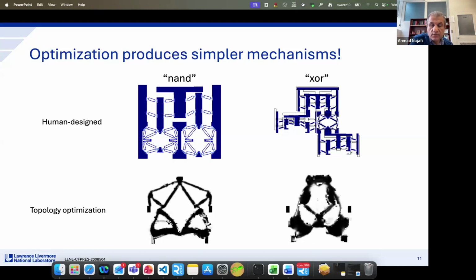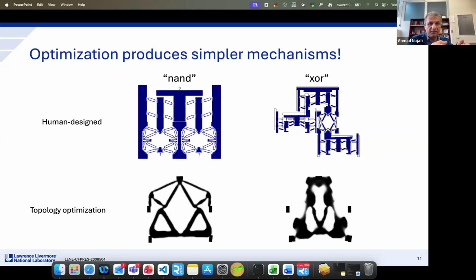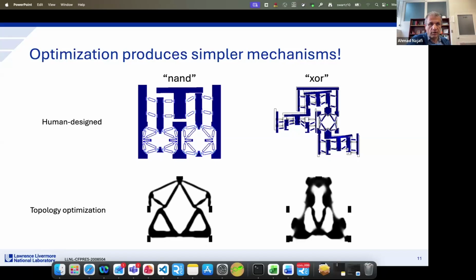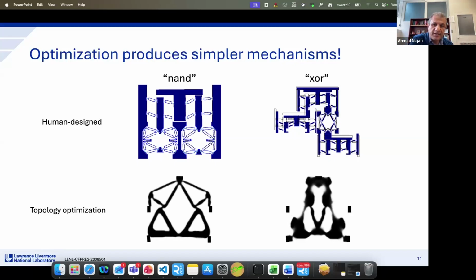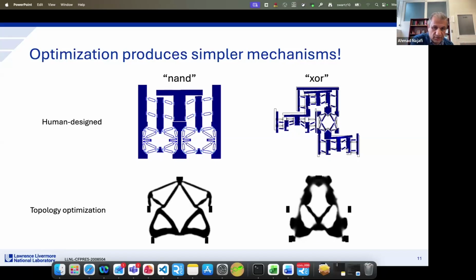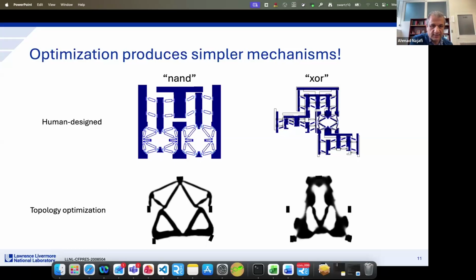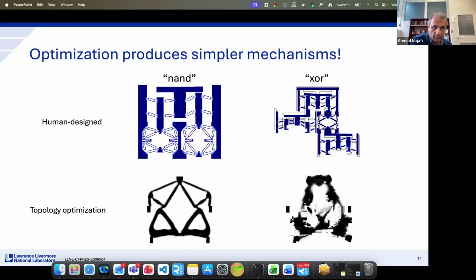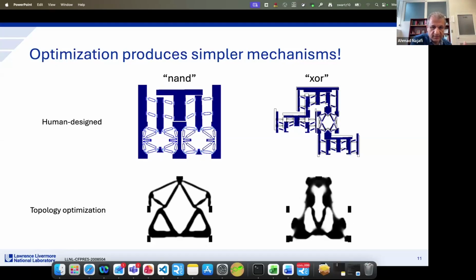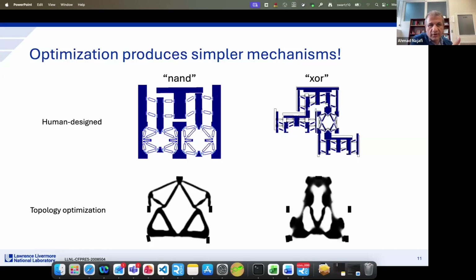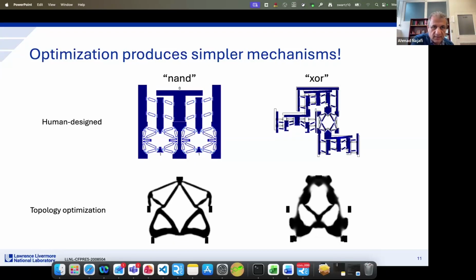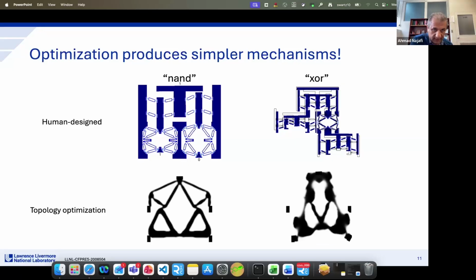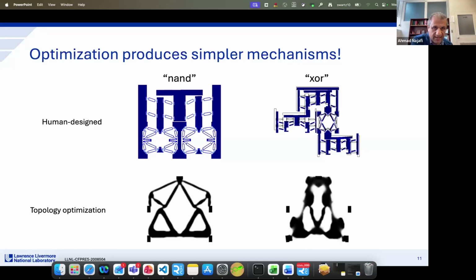Okay, it makes sense. And you saw that one of the issues was that when you try to make it, it was buckling. If you add the buckling constraint or buckling analysis in your topology optimization, probably you can predict or design in such a way as to reduce the buckling in the third direction or any other direction. Yes, so at this point you don't have the buckling in your analysis.